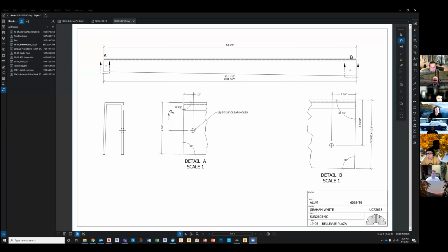These are details, and you can cut details with Inventor. There's a detail tool you click on, and it asks which view you want to take the detail from, and then it lets you show what size cut you want, and you can change this from a jagged border to a smooth border. They place these views in here, and like I said, if any changes occur to the part, these will all get updated. They're all linked to the original part.